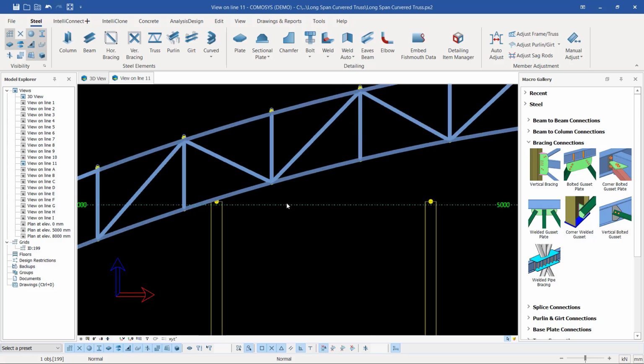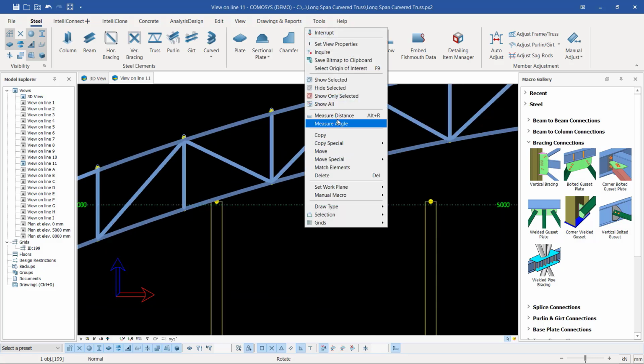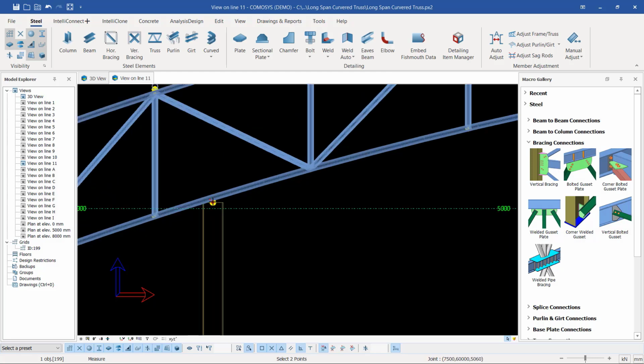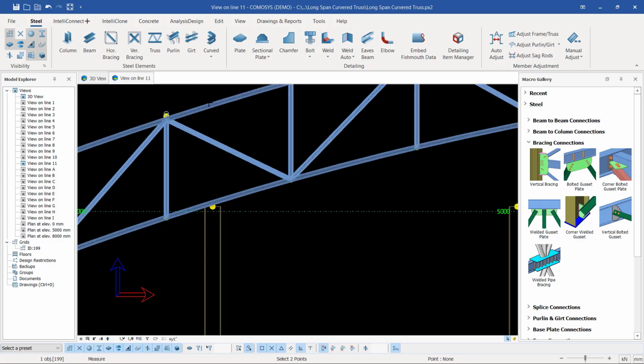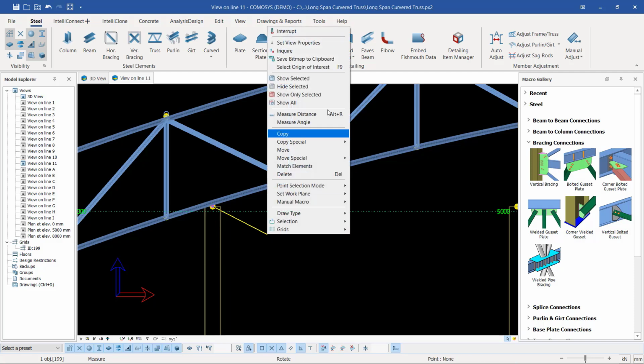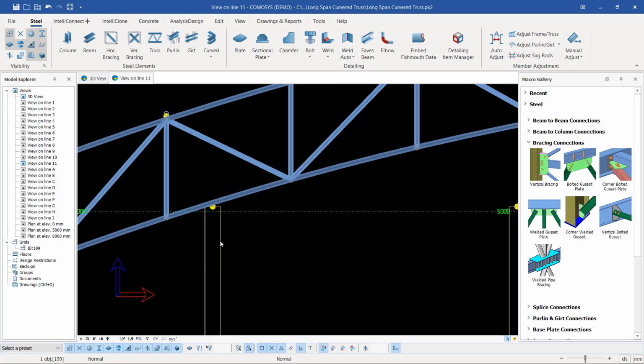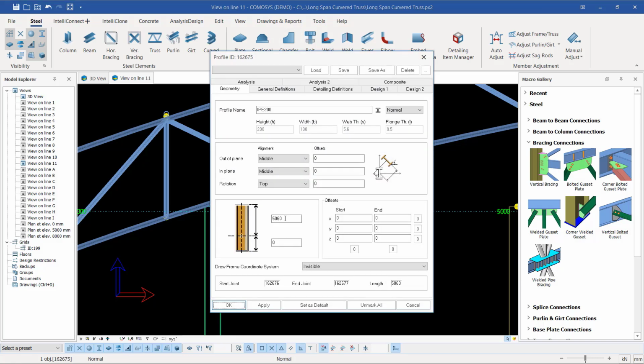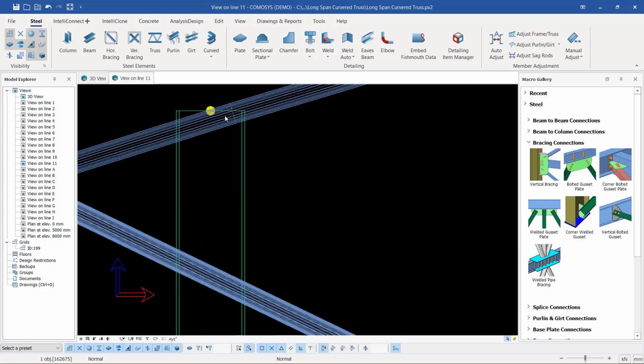Now, to adjust that, you have to right click and come to measure first of all, and try to see the deficit, the distance remaining to make it reach this far end. So you just mouse on top there, and you'll be able to see the adjustment. You can see 12.8 or 1280. So you add that on the current height. So let me just add that quickly, because I don't want to waste so much time there. So I'll just modify this. I'll just add extra. So I'll just type 6336 right there. So if I come here and click apply, I'll be able to see it has gone all the way to that far end.